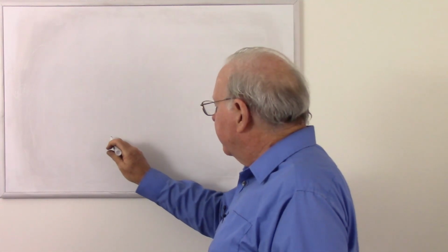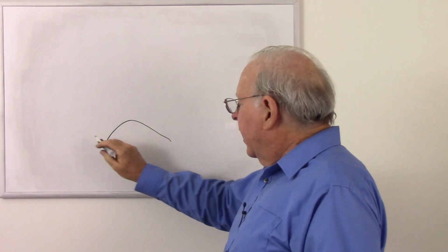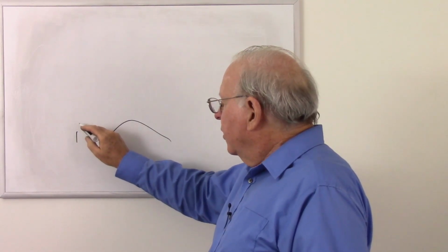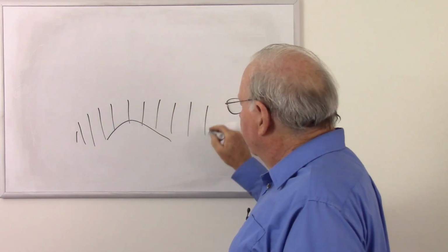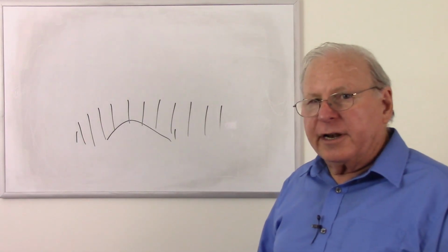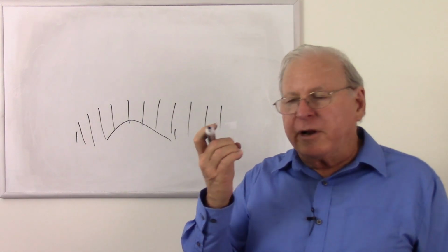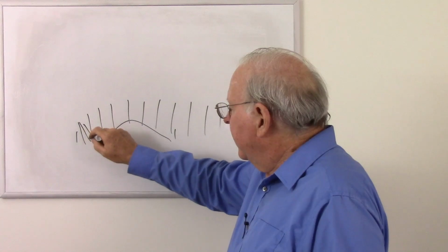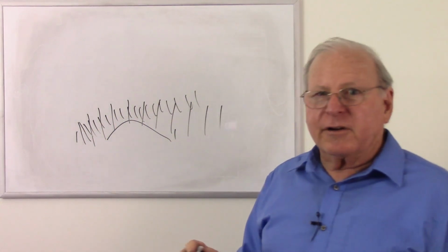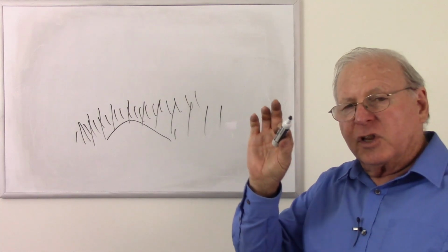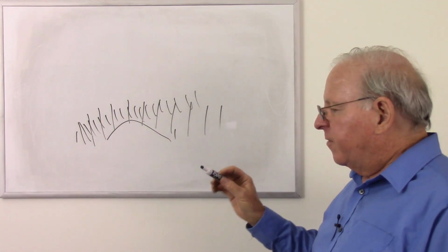So for example, if I have a hill and I'm over here with my antenna, low frequencies will diffract around that hill and I can pick them up with another antenna here. But if I get out with my little 2-meter handheld with the shorter wavelength, no dice. They do not diffract around. So just like other diffraction, the lower frequencies diffract more than the higher frequencies.